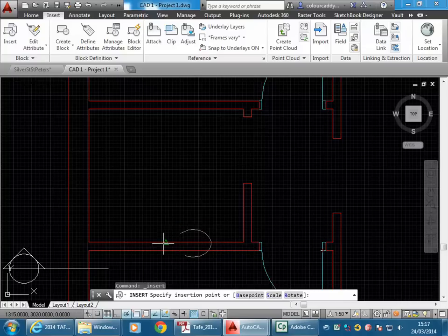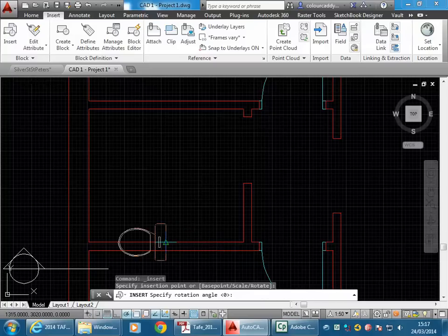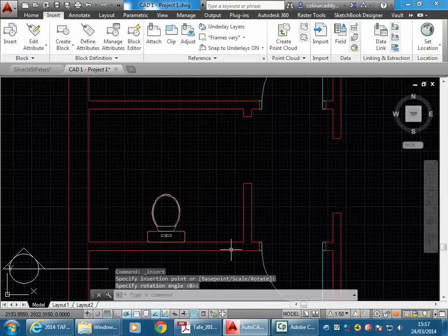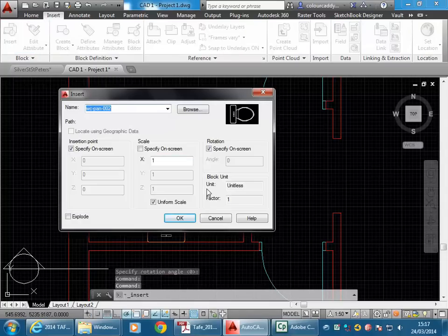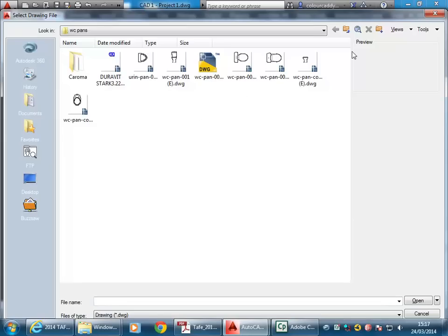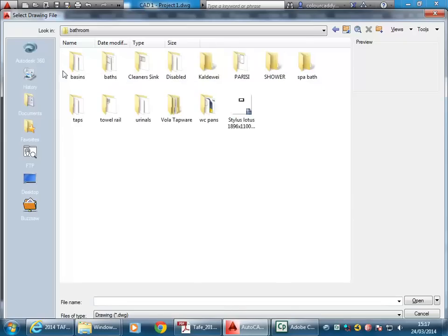So the midpoint there, if that's where it's starting, would be a good base point. The midpoint on the wall, and then if you've got polar or ortho, you can just come straight up and it'll snap to that angle. Right, so then you can just insert the bath and the WC the same way. They shouldn't be very difficult. Just do those really quickly, and then I'll give you some time to try all these things before we get right into blocks.